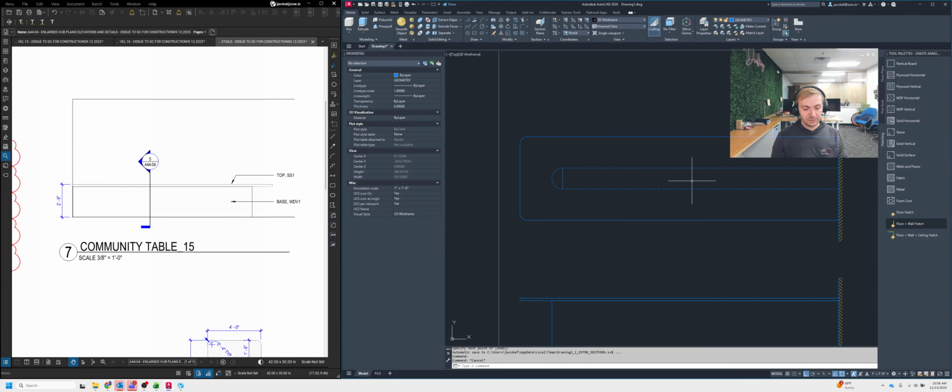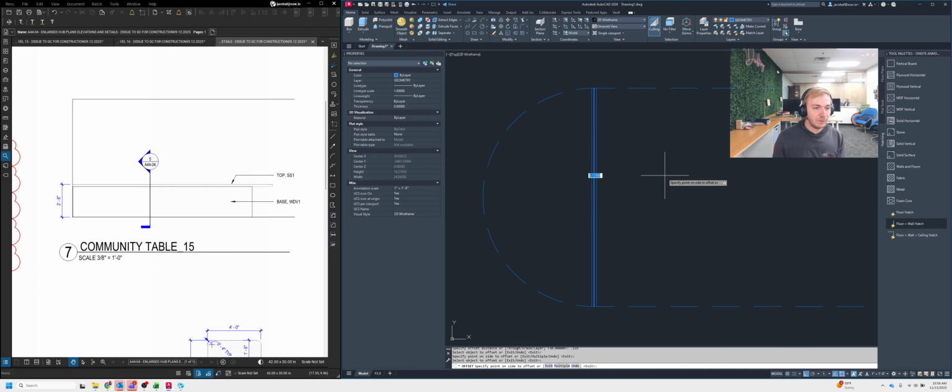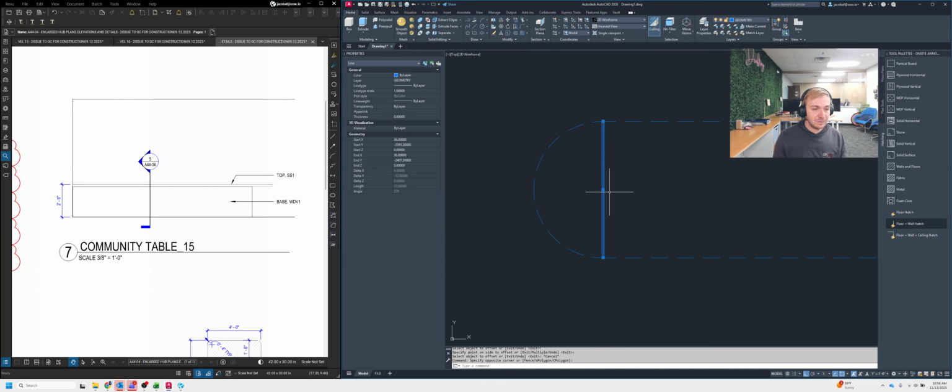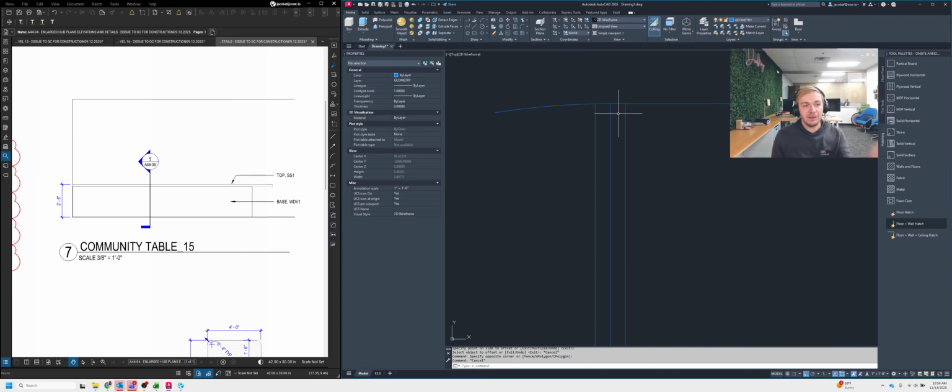All right, so let's go ahead and offset this line. I'm going to offset it 0.125 in either direction off the center, so that I end up with a 1/4 inch reveal at this specific location. I'm bringing it in 1/8 into the curve, 1/8 into the straight panel, and that gives me that 1/4 inch I'm looking for there. Then from there, I'm taking a line from the center of that reveal, and I'm moving it over here to the wall.